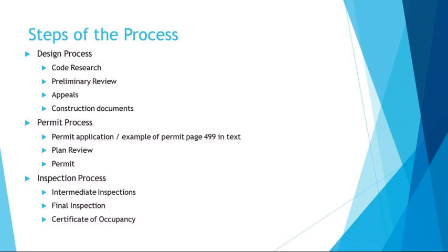If the inspector feels that a condition is unsafe or that the construction is not being carried out in an acceptable manner, a stop work order will be issued. This means that no other work on the site can occur until that particular problem is addressed. An inspection may not always be done by a code official. Remember, some jurisdictions allow or even require the owner to have the construction process inspected by a separate inspection agency.